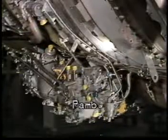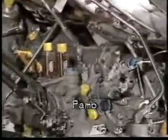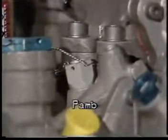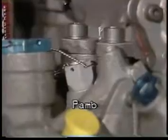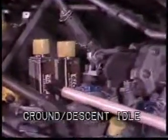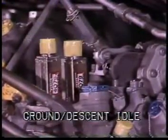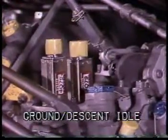P-ambient. This ambient pressure input biases fuel flow schedules during approach and idle operation to ensure engine-supplied bleed air flow meets airframe pneumatic system requirements. Ground idle. This is the normal idle mode and is selected by energizing this solenoid. Ground idle mode provides low idle thrust to facilitate aircraft taxiing.